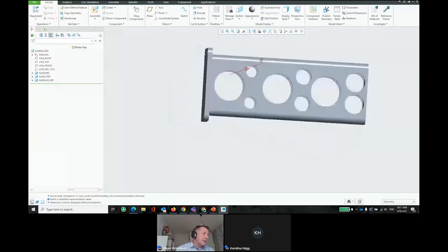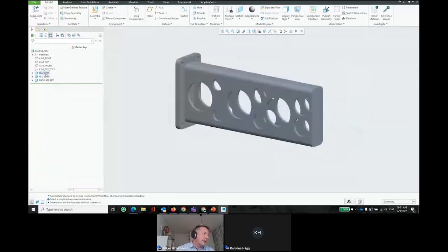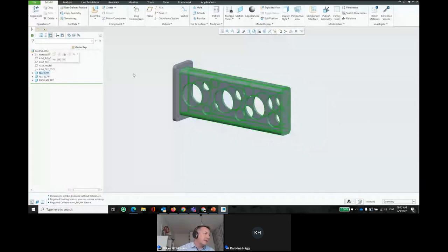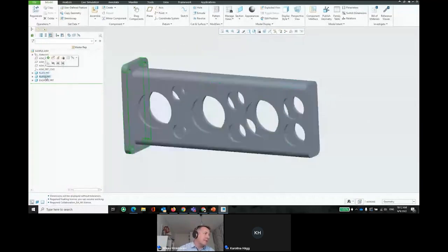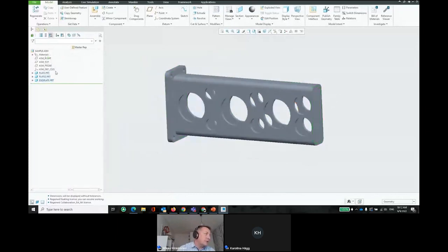So here we have a pretty simple model. We have one end plate. First we gather a bit of licensing here. So let's go now. We have a plate, well, it's basically a beam. Then we have an end plate, and then we have yet another end plate here. My plan is to have this model here as a solid and the rest of the stuff as a shell.